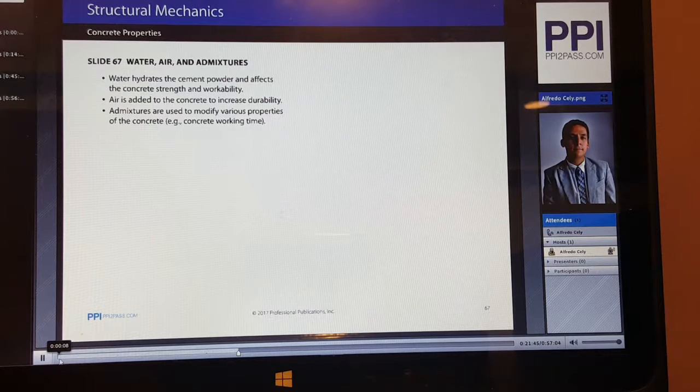Some of the advantages of these admixtures include creating concrete that has a higher strength, a higher durability, a higher chemical resistance, and a higher workability, a controlled rate of hydration, and reduced shrinkage and cracking. Accelerating and retarding admixtures fall into several different categories, classified by ASTM C494. Water-reducing admixtures disperse the cement particles throughout the plastic concrete, reducing water requirements by 5 to 10%.